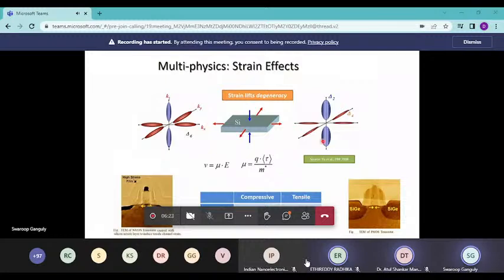So they can only scatter between these easily. The others become more difficult. So since electron scattering becomes difficult, the electron mobility improves. That is the improvement you are looking for here. For the NMOS, the strain is applied differently, by the way. You apply a high stress silicon nitride film on top, which applies tensile stress. It stretches the device, and that has the effect of reducing the effective mass in the channel. So again, by changing the band structure. So the idea behind applying mechanical strain is to thereby improve the mobility.